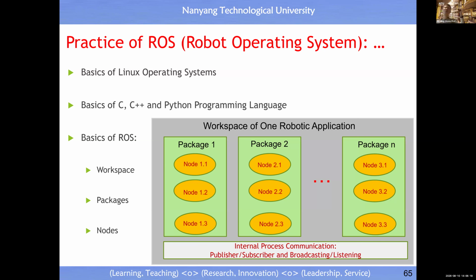One is the publisher-subscriber model of communication. Another is the server-client model of communication. You must think in that way. It provides you two models of communication: one model is publisher-subscriber, another model is server-client. That's it. As a user, you choose whichever one you want to use. So it is very easy to use ROS to build up a distributed system.